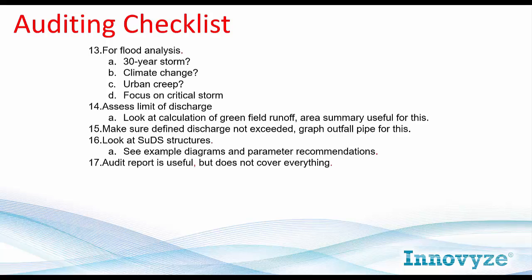There's one other thing, the MAD factor. Remember the manhole addition? This is a correction factor to represent all those little house connections which exist in reality but not necessarily in the model. So as I said, this list will always be evolving as our understanding of how to represent these things improves, and how the software develops and our processes and your processes develop over time. So I hope that's a start.